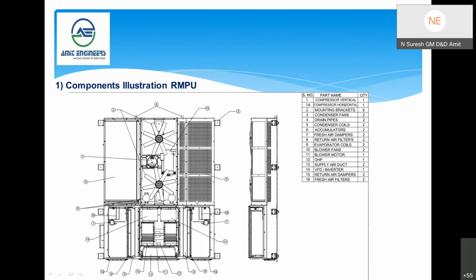In case of 415 volt power failure, this emergency inverter will be able to supply the minimum air quantity as per the standard, so that there won't be any suffocation inside the coach. Even though there is no cooling, a certain amount of fresh air will be supplied to avoid suffocation inside the coach.